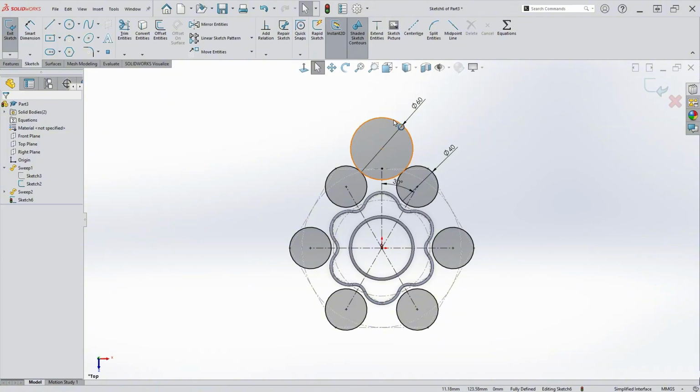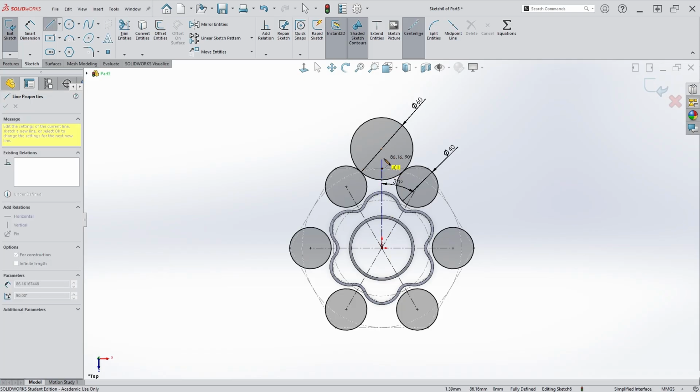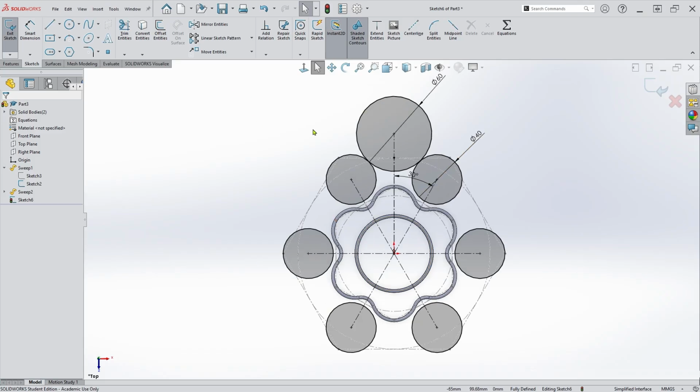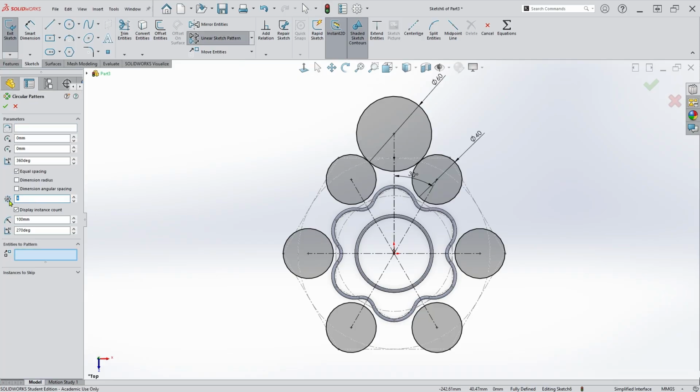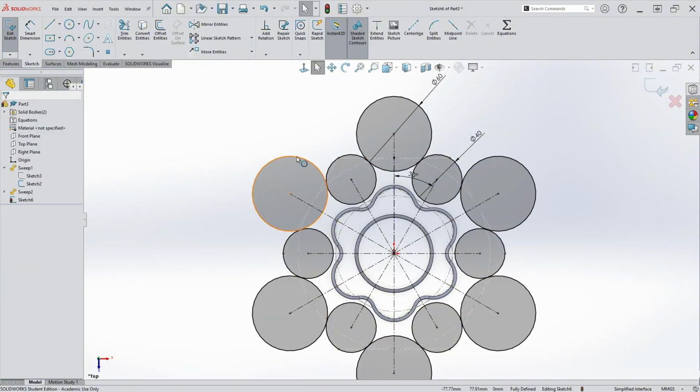All right. Once again, we go to center line, origin, and draw this line up here to the center point. Okay. So we go back to circular sketch pattern, instances, fix, entities to pattern, select the center line. Make sure you don't select down here because remember we have two center lines, one that's on top of the other. So make sure you're selecting this top line versus this bottom line. You can see when it's highlighted. So select this line and this circle. Right click, good to go.